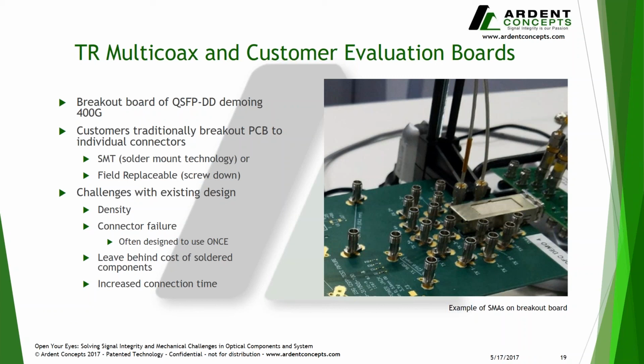Using the field replaceable style connectors, as we are in this example, they are often designed to be used once, and as such, when you screw them down to the board, you can move the center pin, which will cause connector failure. If you are using solder down connectors, there is the cost of leave behinds unless you try to recover them, but recovering them can be a timely process, and most people just assume it as a leave behind cost. As a result of having many individual connections too, there's increased connection time within the labs, and time is money.